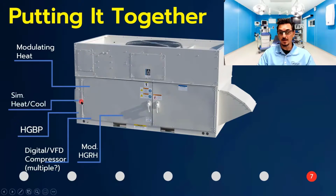Simultaneous heating and cooling is the auxiliary reheat. So if you have electric heat in this unit, you want it to be able to run at the same time as your compressors so that you can get a little bit of that extra reheat on those extremely rare cases where you don't have enough hot gas. It's a nice idea to have a variable speed supply fan. I'm a big fan of variable speed condenser head pressure control because the head pressure, the ability to control that consistently affects everything else in the refrigeration cycle, so that's nice.